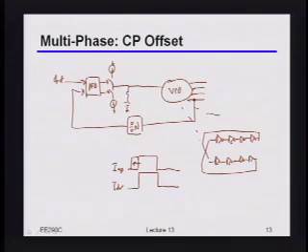Okay? So it turns out the way you can actually do this is quite clever. If you want to intentionally introduce an offset, you just intentionally skew the up and down currents. In this particular example, whatever CDR control bits you had, you would use those to program the down current relative to the up current.